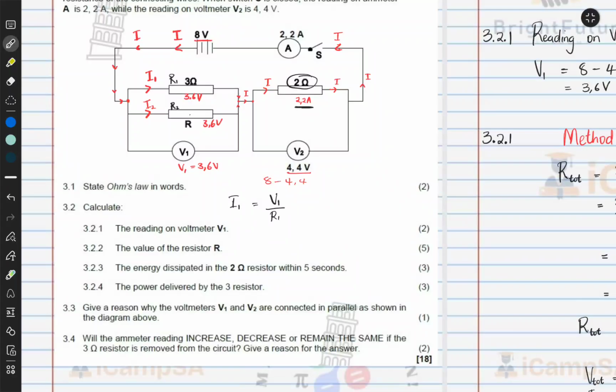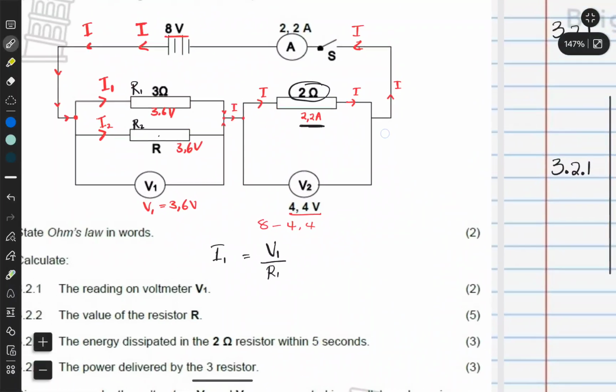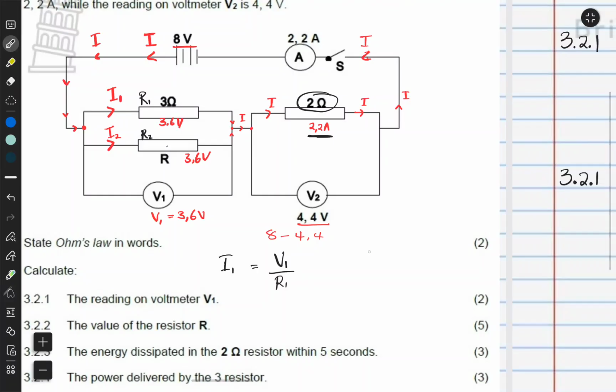So that's why, because it measures the potential difference and it has a high resistance. So unlike an ammeter, a voltmeter has to measure between 2 points like this. So it measures here and there. So the difference in electric potential. So it has to be connected like that. If it was just connected in series, it would not be able to do this effectively, because the current wouldn't flow there. It would be an issue.